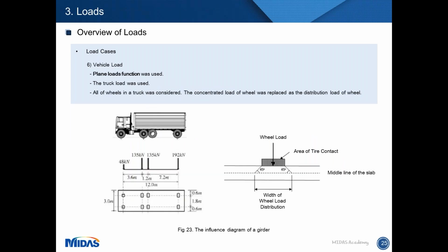The next one is vehicle. The vehicle load can be considered as the moving load cases of MIDAS Civil. The moving load analysis of MIDAS Civil is based on the influence line and surface analysis. It could be time-consuming work, so I used another method.